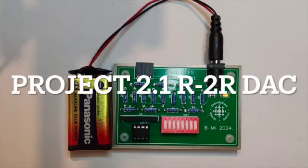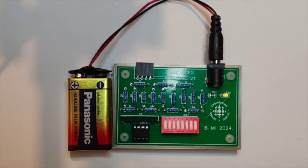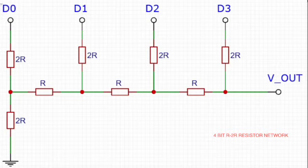Project 2.1, the R2R Digital to Analog Converter, or R2R DAC. The R2R DAC is a simple and effective method of converting digital signals into analog voltages through the use of a R2R resistor ladder along with a voltage follower op-amp. Here we're using the LM741. Now let's take a look at how this circuit works.